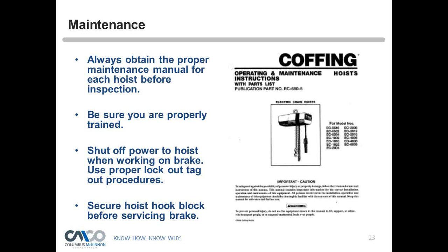Don't work on a brake with the power on. So you want to use proper lockout, tagout procedures, as well as if you're going to disassemble or even working on the brake gap, you want to secure the hook lock. Meaning, if you were to by mistake make too big of a gap, you could release the hook lock, which is heavy.